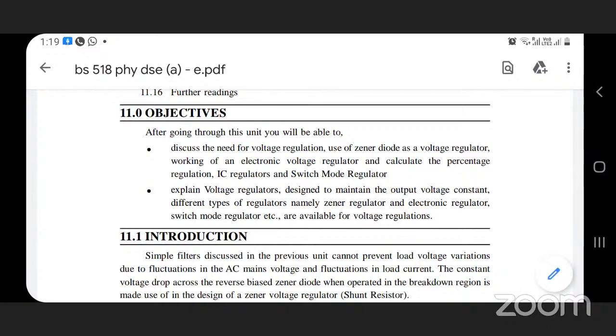When the lower voltage is coming out, the diode is not going to conduct any current. That means for stabilizing the voltage in the case of stabilizers, the Zener diode is to be utilized in the reverse bias condition. Whatever fluctuations take place here, the diode is not going to conduct current at all. That is to be noted. That's why you need to use the Zener diode as a regulator, for voltage regulation.